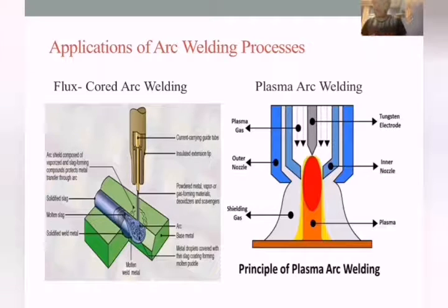Also, for the non-consumable electrode, as you can see, plasma arc welding is basically plasma gas working with a tungsten electrode, and the tungsten electrode is not representing a huge part of the metal that is being worked on. When the force of the plasma gas and the tungsten electrode is applied down, there is also shielding gas that covers the workpiece from being deformed by oxygen, as we know that oxidation strongly influences the shape of the metal. Moving on to my friend Muhammad.